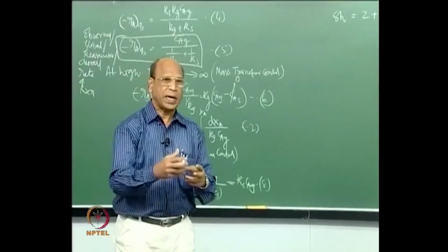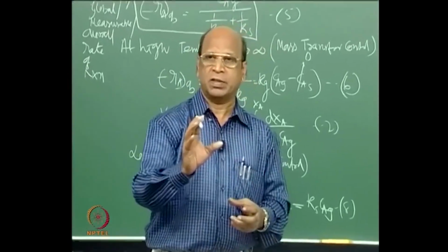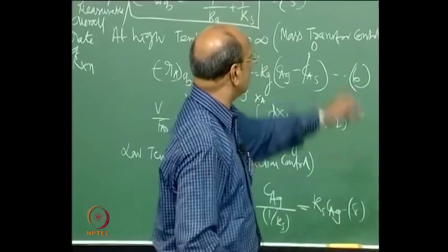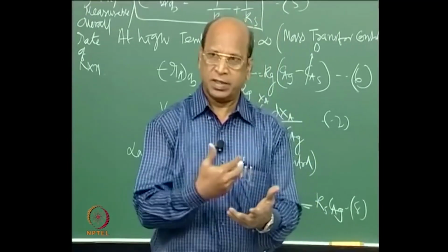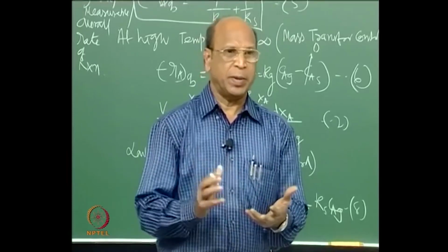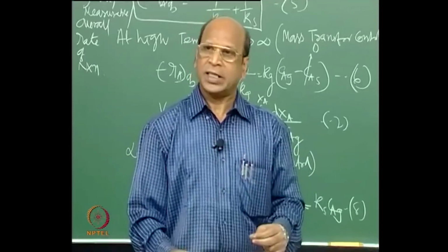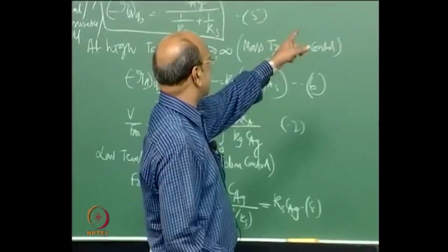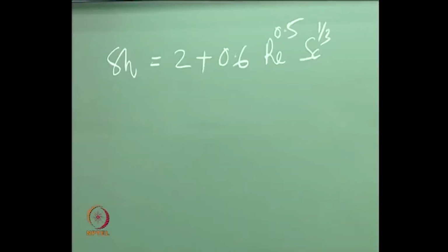The mass transfer through the packed bed is slightly different, and if I take a fluidized bed, that is different, and all the equations are in terms of only Sherwood number, Schmidt number, Reynolds number. You take any equipment like packed bed, fluidized bed, moving bed, rotating drums, the mass transfer equation contains only Sherwood number equal to a function of Reynolds number and Schmidt number. That functionality we have to find out only through experiments, right.